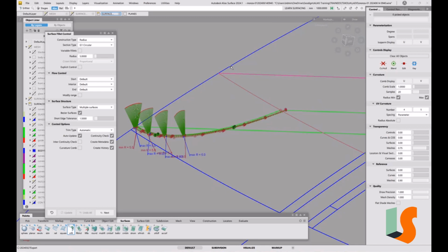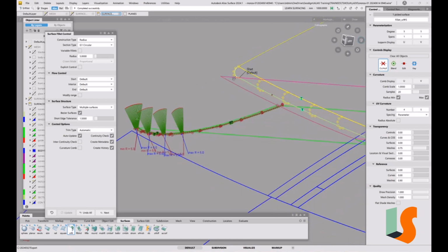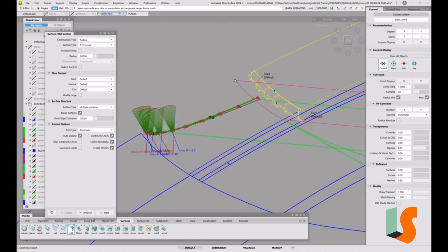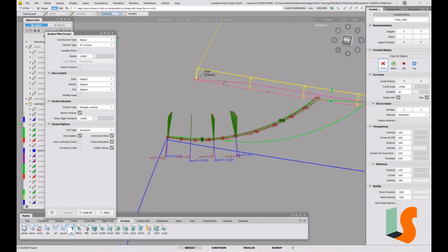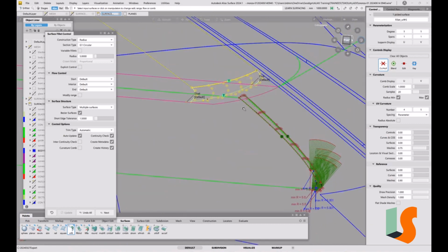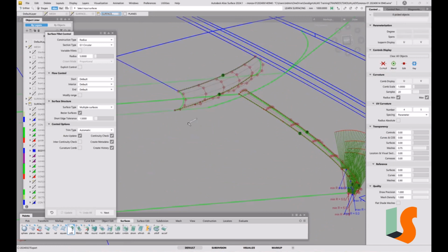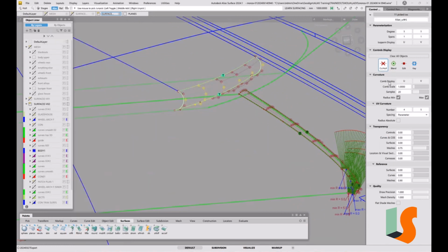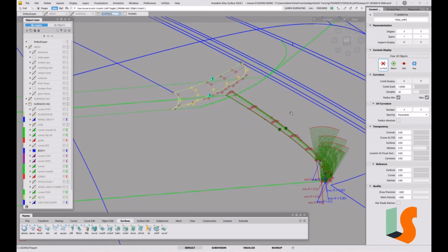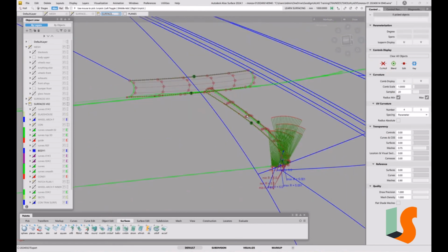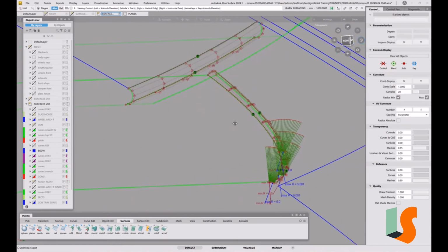this is a quite sharp edge there. So I need to make sure my normal's around the right way, otherwise I'm going to get the wrong fillet. Now you can see how much that cuts that back. So we've set up our line here, but it's cut it right back to here. And also that fillet looks enormous compared with this one, but actually when we measure the radius of that, it's exactly the same. It's 5 mil, and that's what happens when you've got a completely different angle between the surfaces.